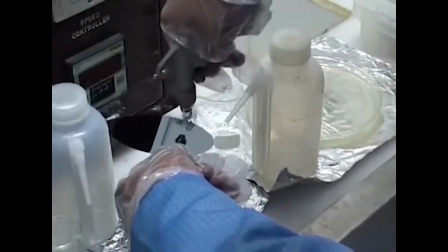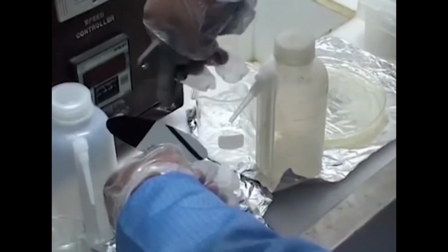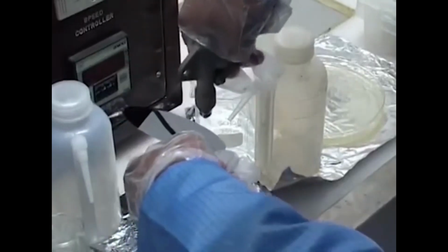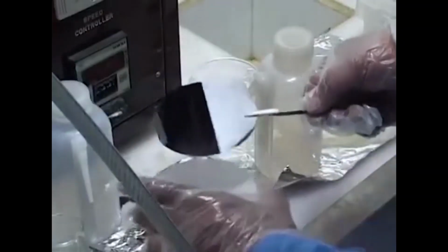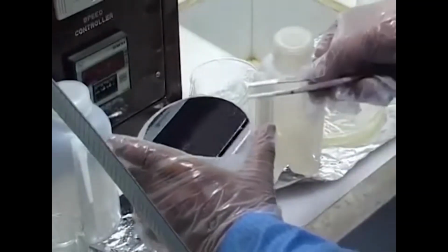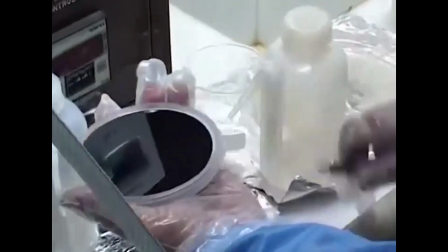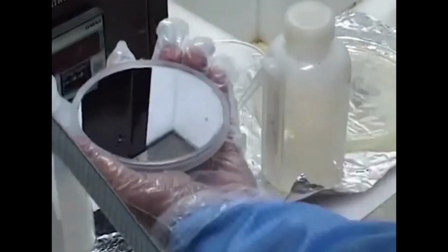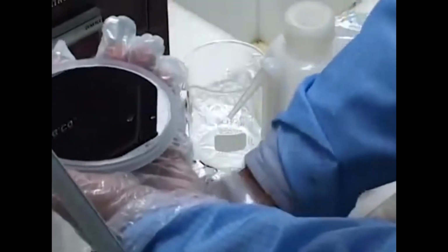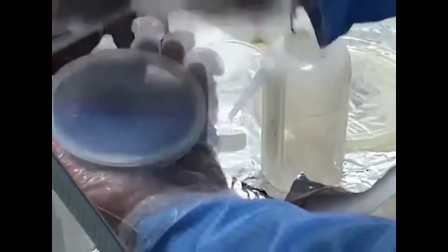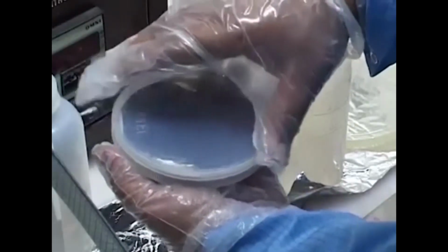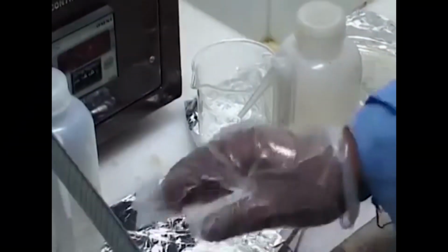So we put this sample, this clean sample, back into the wafer box, as you can see, and then we'll actually do a heat treatment of this particular wafer so that it can get rid of all the water from the surface, and that way we have a completely dehydrated surface. We need to cover it at this stage because the moment we move it out of this clean area, it can again become dusted and the contamination of the surface may happen. So this is how the Piranha cleaning process of the wafer is done.